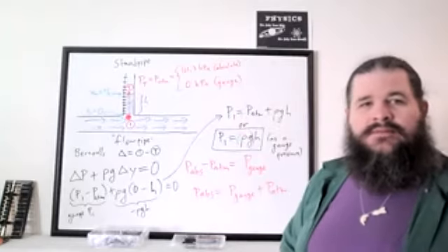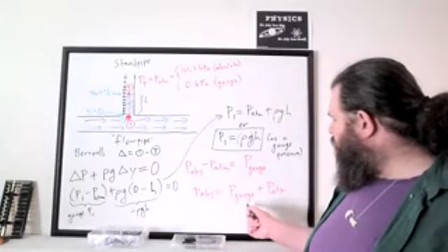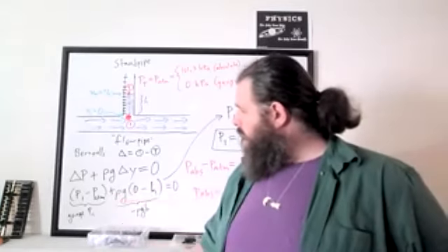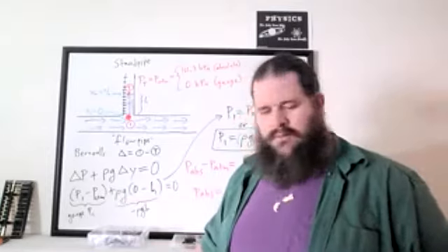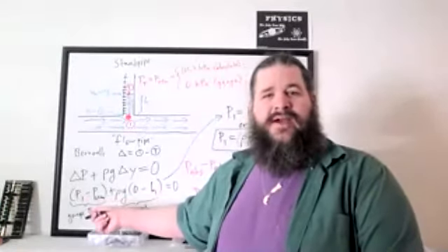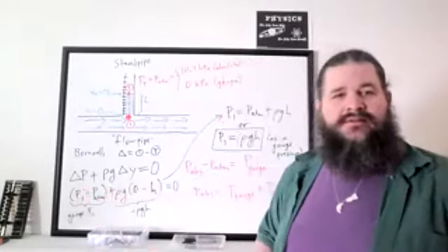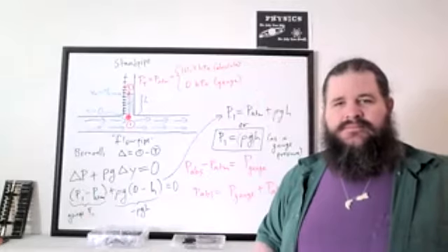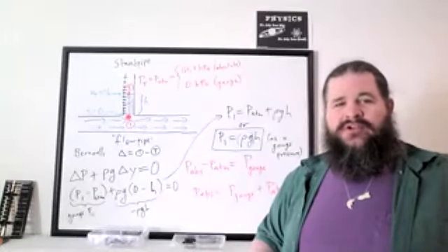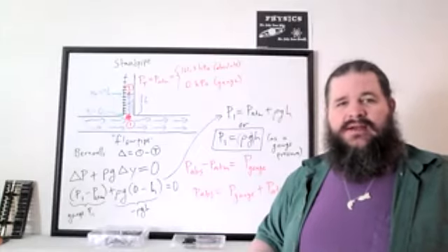Okay, and then for the equation on the bottom, on the other side in black, that first part in the parentheses, how did you know that that was equal to gauge pressure? This is just how gauge pressure is defined. Gauge pressure is defined as the difference between the pressure at that point versus the pressure of the atmosphere. Okay, thank you. And you could be using absolute pressure or gauge pressure in any given Bernoulli equation as long as you're consistent about it.